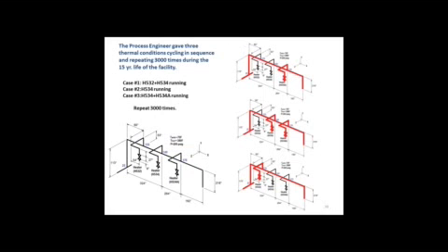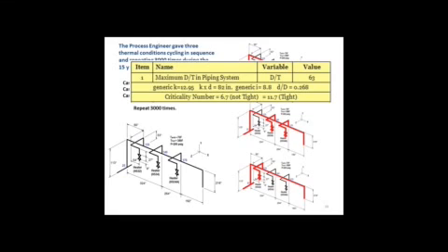Now let's go to a little bit more realistic condition. This is something that you generally would deal with. This might be your gorilla, especially if this was larger diameter pipe, because here you've got multiple operating conditions. So now you've got interaction between the different branches, and the branch flexibilities in a tight system will tell what stresses result when these systems interact.